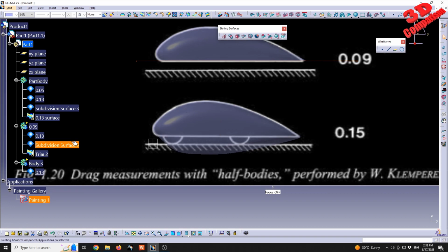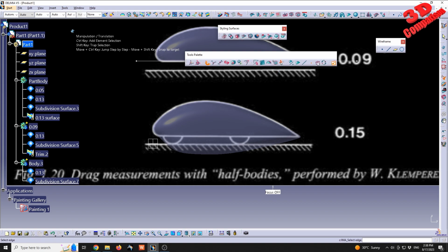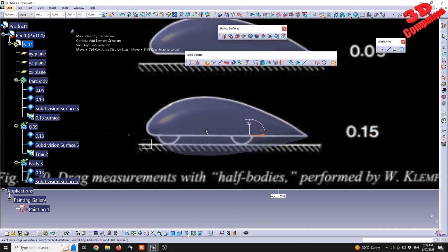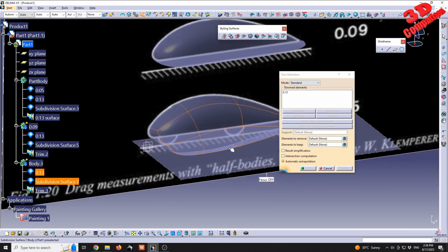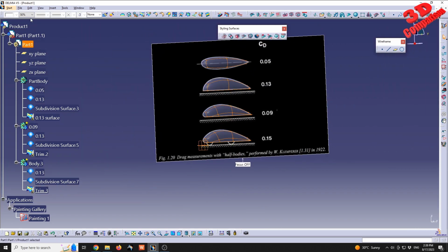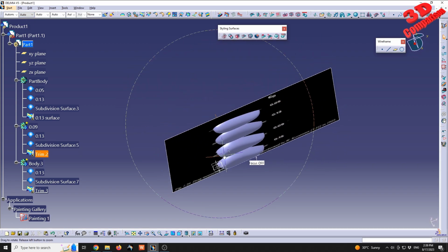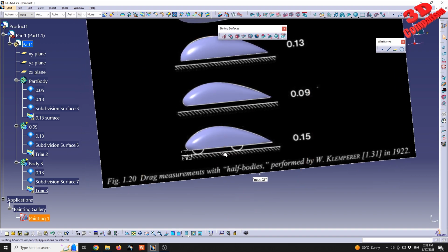Now I'm just gonna copy again this plane, so that subdivision, paste, have it dragged into the desired location, which is this one, and have that trimmed again by going to trim, trimmed elements, surface and plane, and just with other side swap until that shape. Okay, now I will remove that transparency to better see those shapes, and I will just add some wheels to the last design.